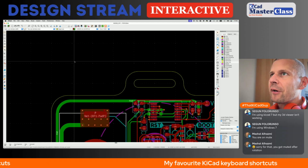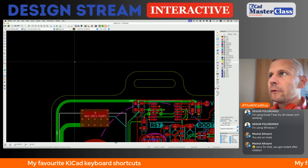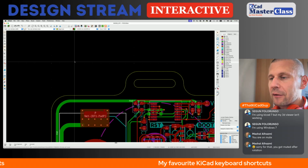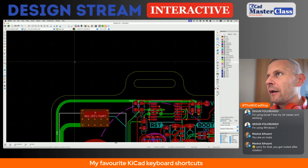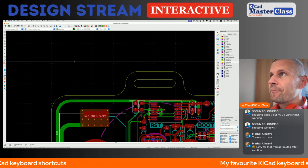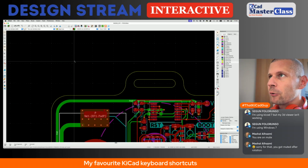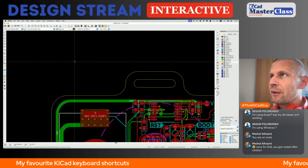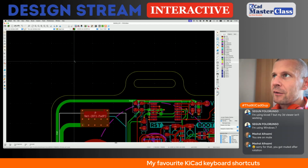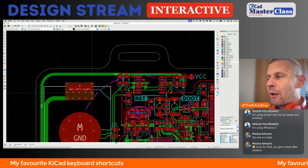Next, grid, very useful. A very useful keyboard shortcut. It's the key N, like natural N, and it means that from the current grid setup it goes downwards, from 0.5 millimeter to quarter, 0.2, 0.1, etc. When you're holding Shift and pressing N, it goes upward. So sometimes I use it, for instance, when I'm routing.